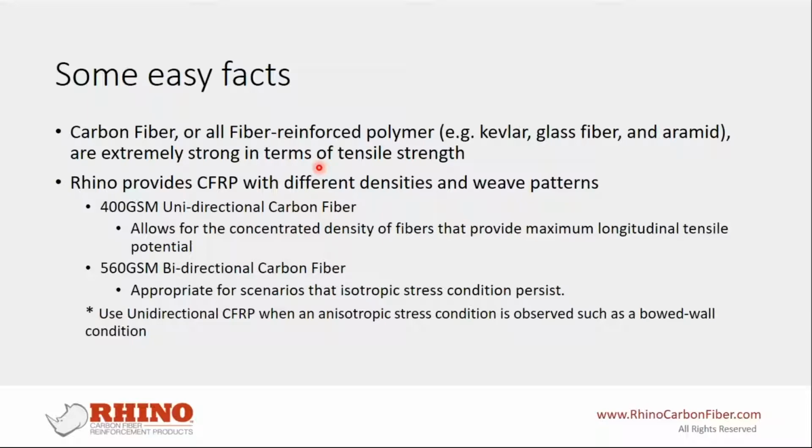Using heavier CFRP will give you higher strength, that's for sure. That is the general trend. But you have to know that as a contractor, you need to spend more effort to saturate the CFRP with epoxy. But anyway, if you are an engineer or contractor and you need some CFRP for a specific project that we don't have in stock, just simply tell us. We are the manufacturer and we can work this out together.